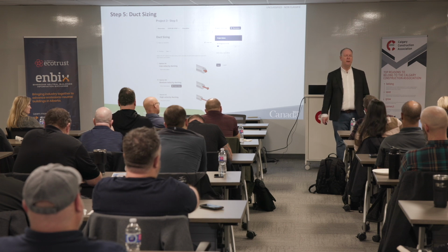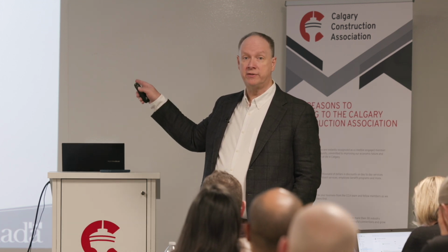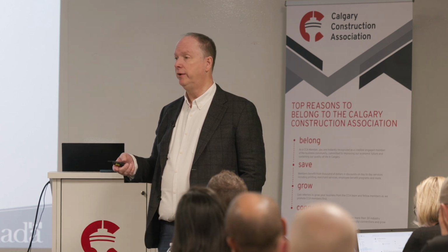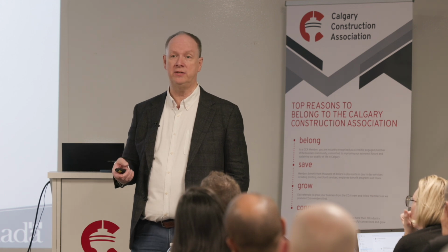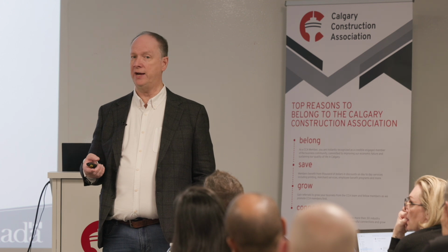Yeah, that is very common when you get into these things. One of the caveats that I have with the mid-velocity system and all the other stuff that we're about to talk about is none of this should be entertained without a proper mechanical design. What happens with a lot of the high velocity and the mid-velocity stuff is somebody will come in afterwards and put a single stage AC in there without actually thinking, this is a high velocity system, I probably have to think about what my CFMs are going to be and how much air is actually running across that coil. That was a conversation I had with the customer.